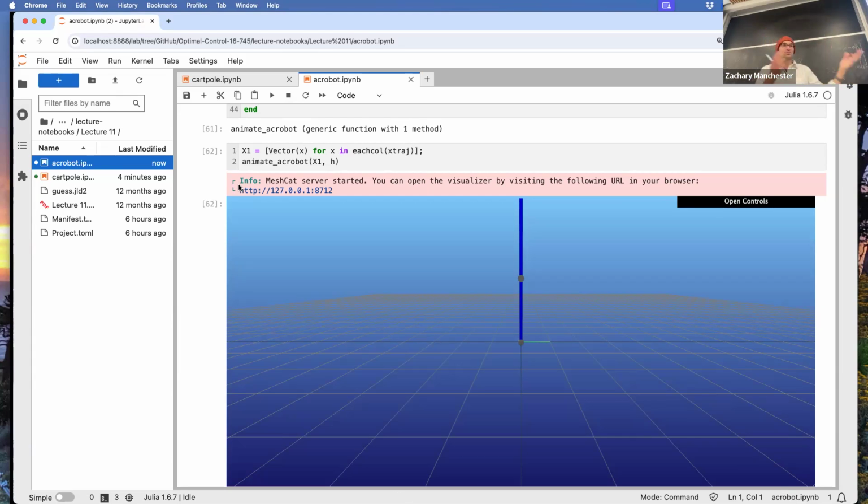In this case, there's a handful of different solutions that have almost the same cost and look pretty similar, and it's total random chance which one you end up in. Here we found two different local optima, basically. In practice, most of the time, we don't really care. In robotics applications like this, as long as it's getting where we want, obeying the torque limits, and doesn't look stupid, we're pretty much fine with it, right? There's actually an infinite number of possible swing-up solutions here.